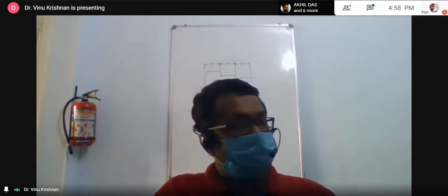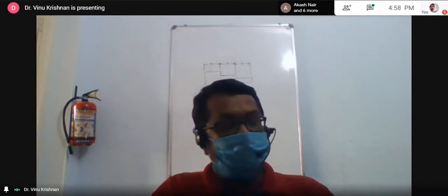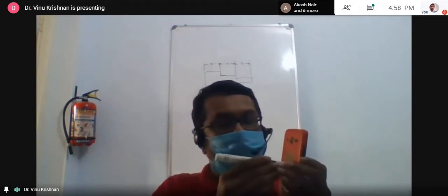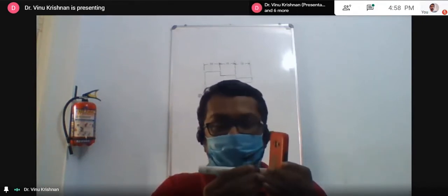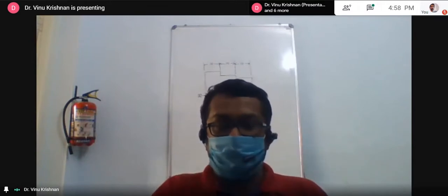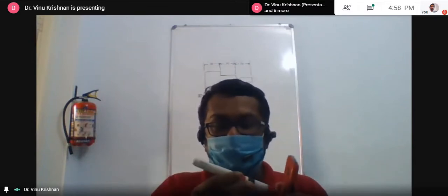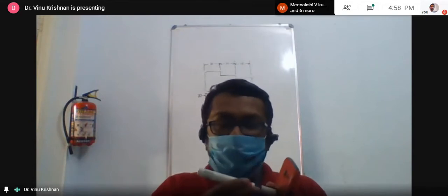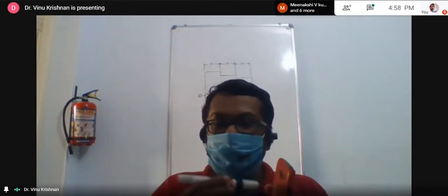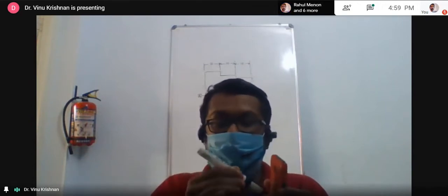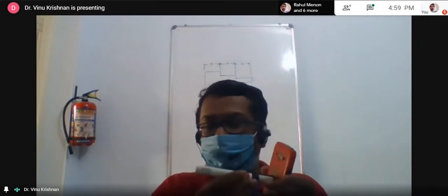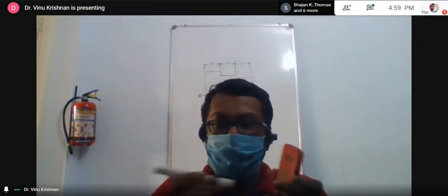Then what you have is perpendicularity. Perpendicularity means how one thing is perpendicular to another surface, just like this. And angularity. Perpendicularity is a special case of angularity where the angle is 90 degrees. So for all other angles you have the angularity callout.